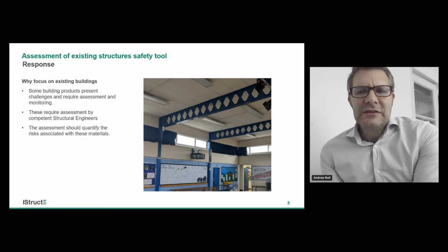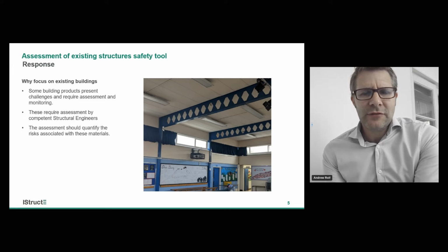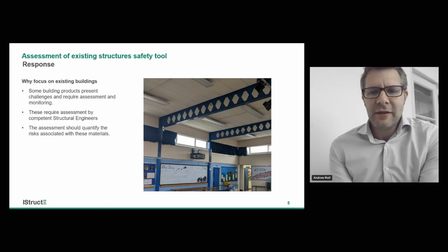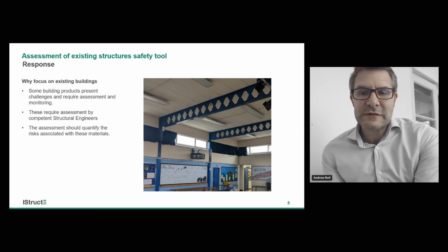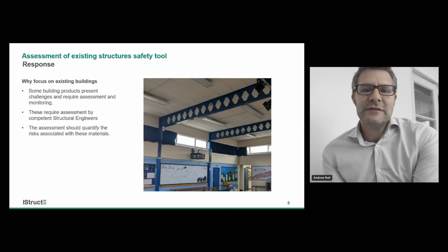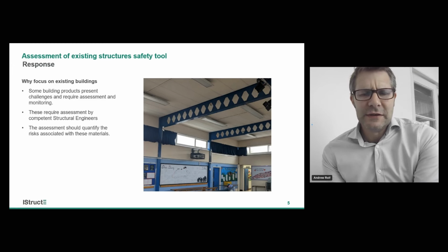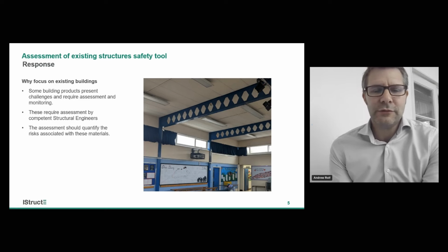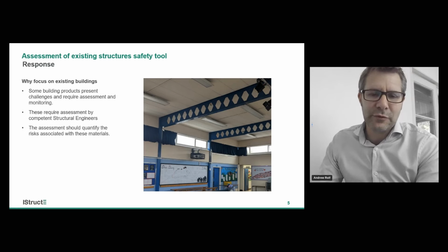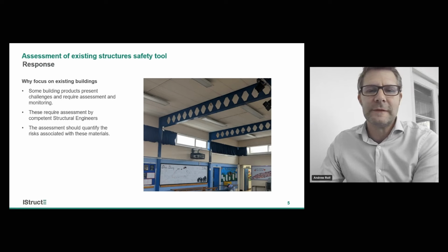And as a result of that aging building stock, the materials and those design practices that they were constructed from are historic, as I mentioned, and systems such as RAAC or LPS systems have highlighted the need to better understand how building products were used and their limitations, as well as the impact that the age and the environment will have on these materials. So the nature of our appraisals will become more complicated, and we're likely to be facing more challenges around overutilization.